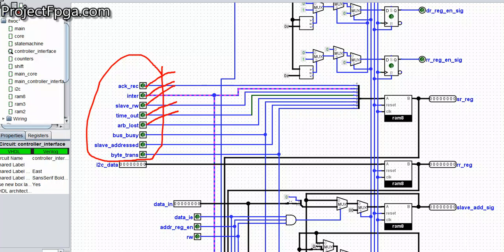It is going to win because it's an open drain. The line is usually high. So whenever any of the bits is set to 0, the slave with the higher address is usually the one that has more ones. So the one with the lower address is going to be communicated with.